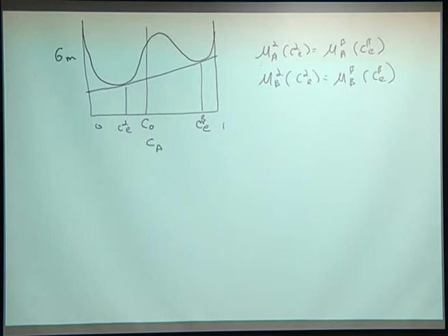And it's not, because this composition is a conserved variable. Okay? And because it's conserved, you're not allowed to change this thing such that you can move it all the way over to here to get to that lower energy. Okay? So that's a very important idea. So composition is conserved. And this idea of conserved versus non-conserved will become important as we develop our phase field models.